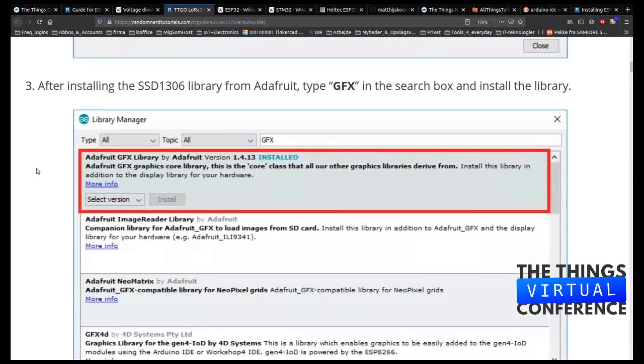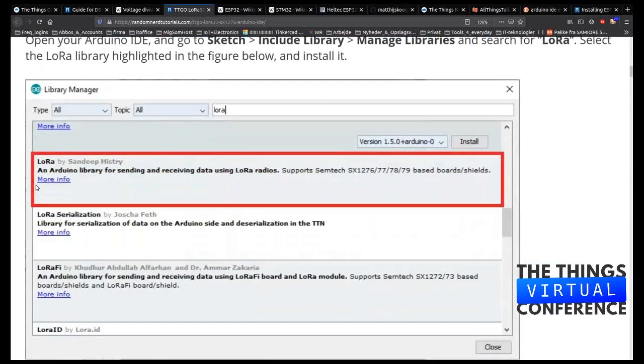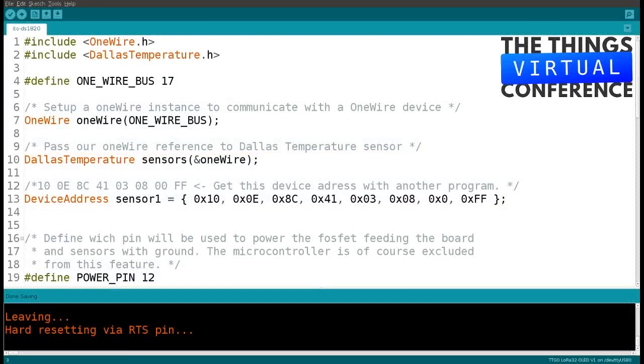So you can install it via the Arduino IDE library manager, or you can download from GitHub and then put the libraries in there, equally to the other libraries, and then call them in the software with #include something.